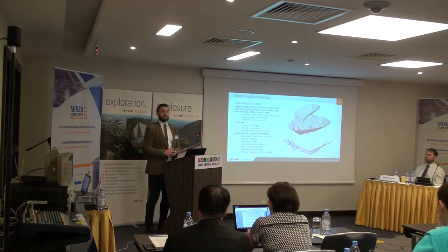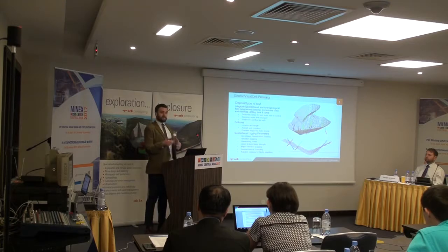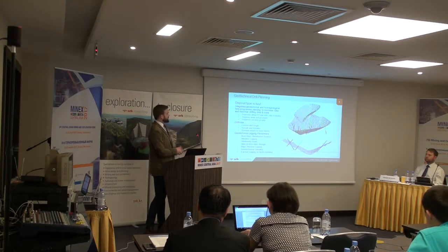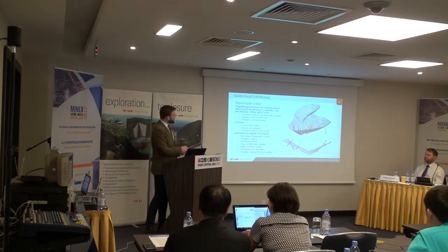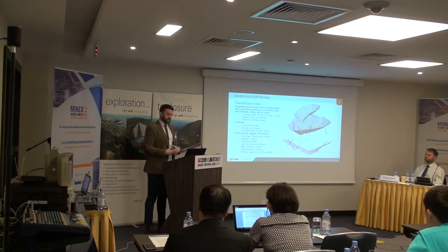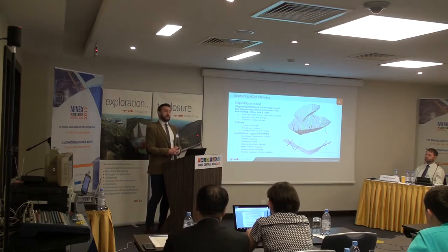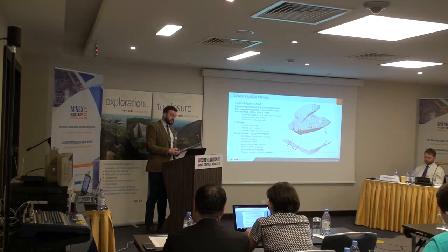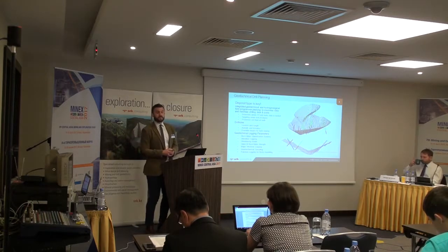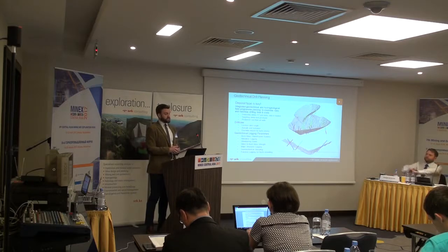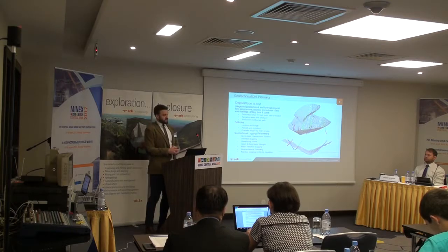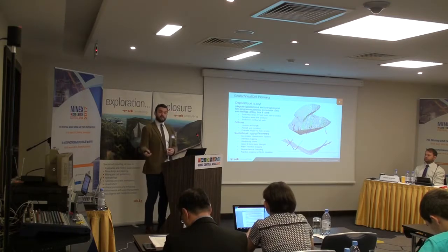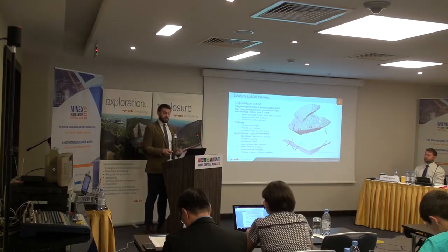And where the value comes is really integrating both your geotechnical studies and your hydrogeological field programs, so that will maximise your data and minimise the drilling times and costs. And where we're seeing or adding more value to projects recently is partnering with the resource drilling and collecting geotechnical data from the resource drilling, and then subsequently using the holes after they've been completed to do hydrogeological monitoring and groundwater testing. So you really need to determine where your geotechnical data and hydro data is needed, target the waste and your mineralisation, also production and final pit walls.